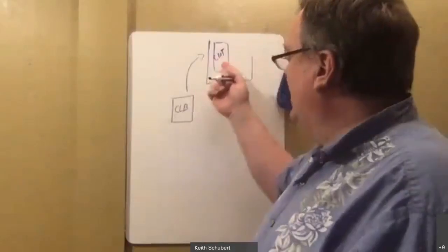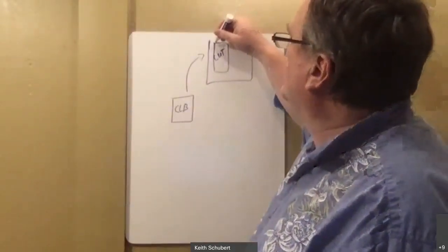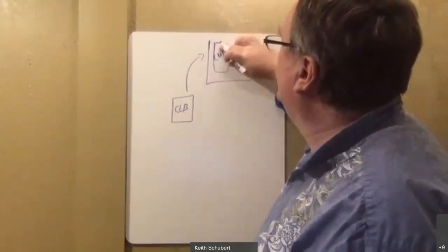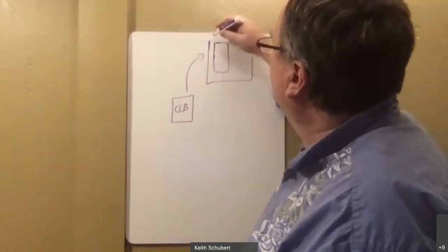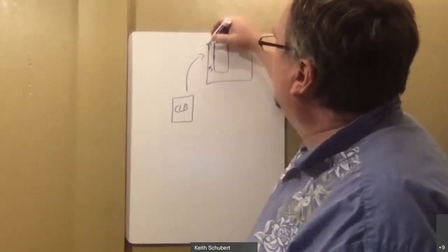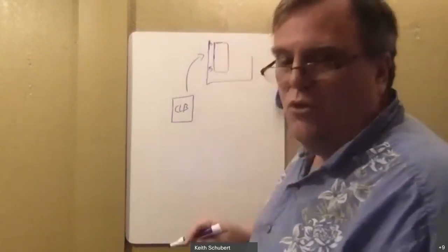This is what does your actual logic. It's got 4 addresses that tell it which one of the lines. 4 addresses gives you 16 inputs, and these are numbered from 0 through 15. The 4 bits of logic that come in pick which line you're on.